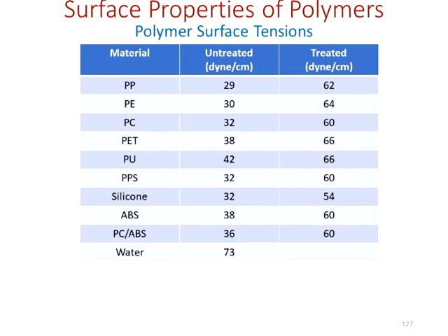So all of these you look at, this is one of the important factors to understand about the surface property of untreated polymers and plastics. They don't wet. Okay. However, you can change them and treat those surfaces so that they can wet. So, for example, a manufacturer wants the appeal of the polymer, wants the other properties of the polymer, but they want it to wet. They want it to take a little bit of water. They want water to wet it so it can be wiped down or washed down or what have you, or whatever the application is, or maybe it's going to move from construction to textile. Then they might treat that polymer surface in a way that allows it to be more wettable.